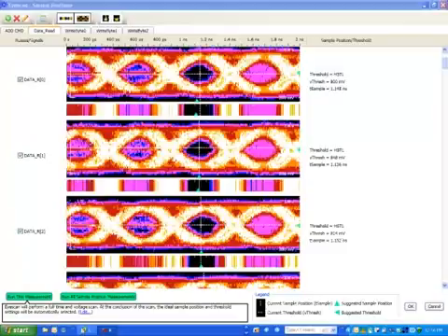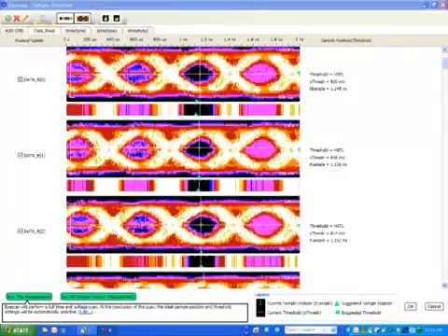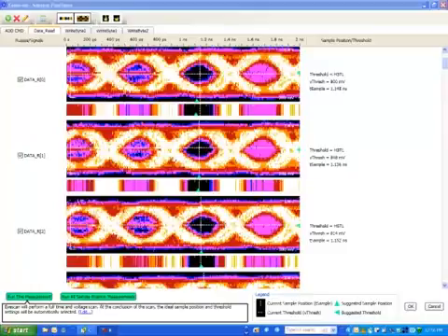Observing the read data bit by bit, these eyes are a composite of all valid data in a read burst. The pixels can be as small as 5 millivolts by 5 picoseconds. The U4154A has unique sampling hardware and software tools that provide the eye scans of only the valid read eyes and write eyes on each signal. We are viewing the read eyes.